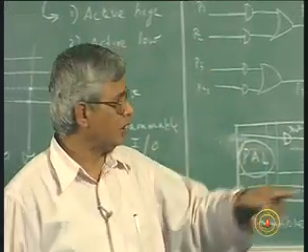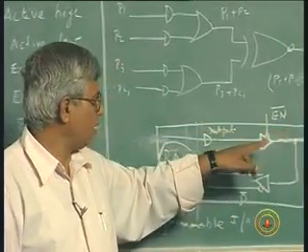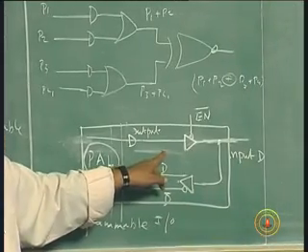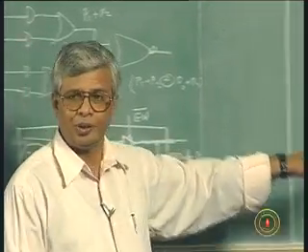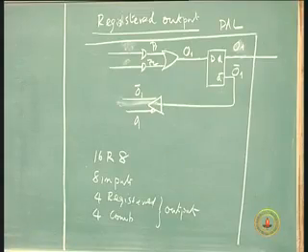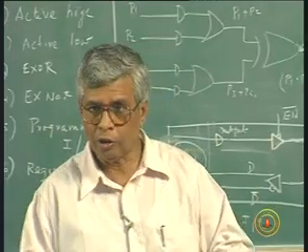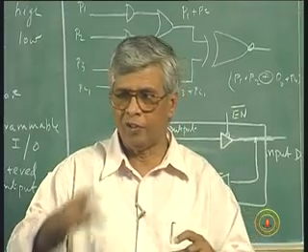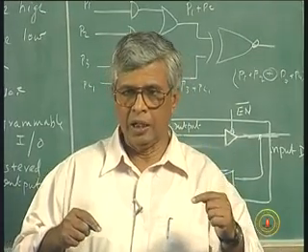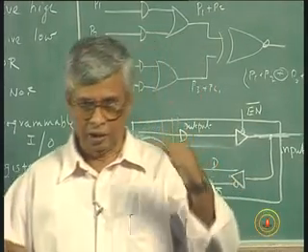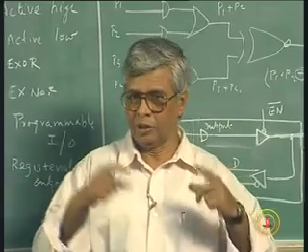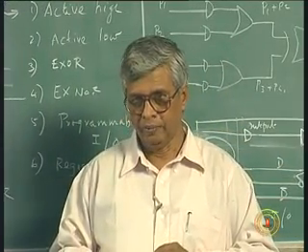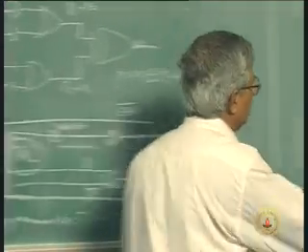But then when you have this programmable feature or this feature, you need extra inputs. You need a clock signal, you need an enable signal, all of them also have to be given. So when I decide the number of pins required, number of inputs, number of outputs, this ground and power supply, is there a clock required, is an enable required, all those things also be accommodated. So clock comes from, so this has to be clock, remember.